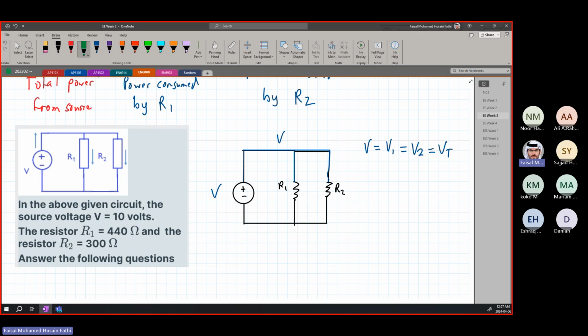However, if you notice now the current, when it's flowing, it is changing. Here, the wire splits into two. The current is being split into two parts, not into half. It depends on the resistances, but it's being split into two parts. One is going in this direction and another one is going in that direction. So here the current is the same. And here, if I use the orange, the voltage is also the same.